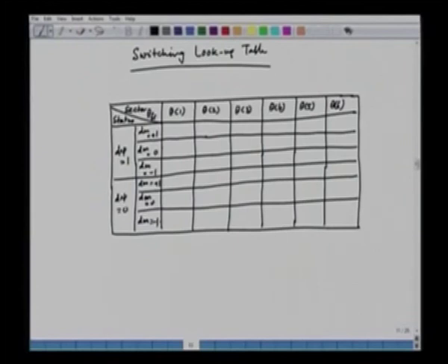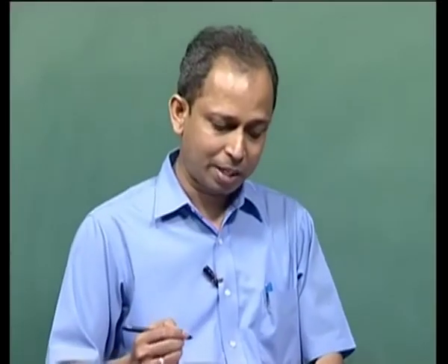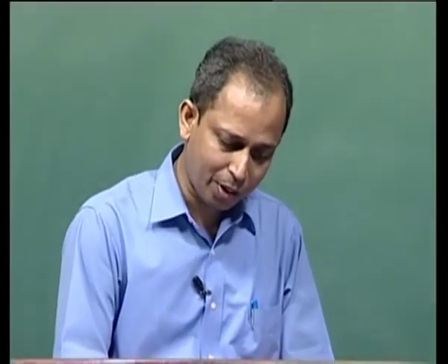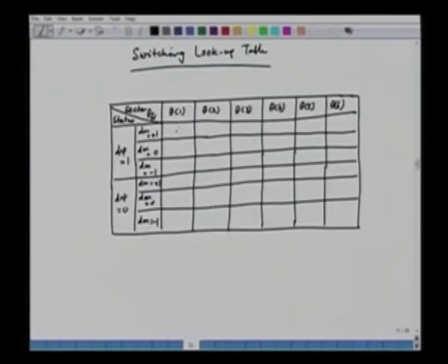So we have to select a suitable voltage vector so as to fulfill the torque status and the flux status simultaneously. So for example, if we concentrate on the first element of this lookup table, we have d psi equal to 0 and dm equal to +1. It means we have to increase both the flux and the torque.